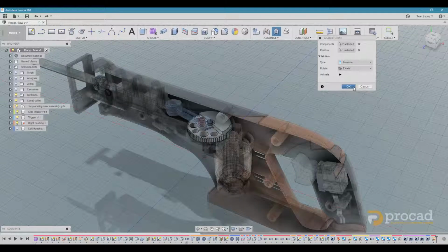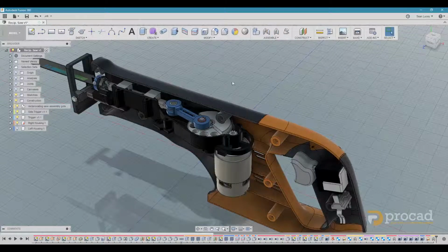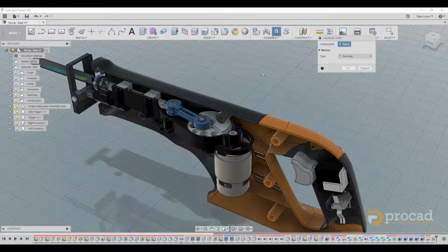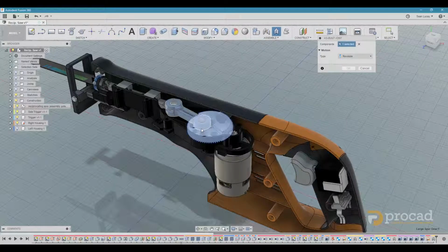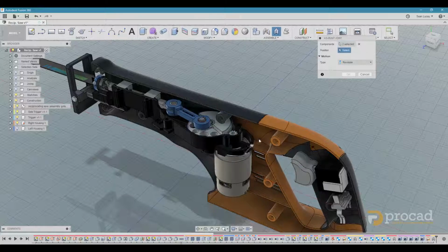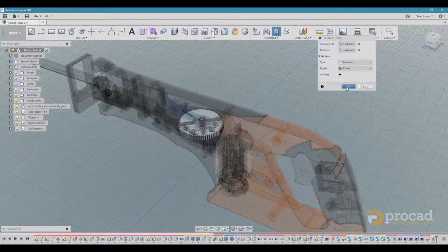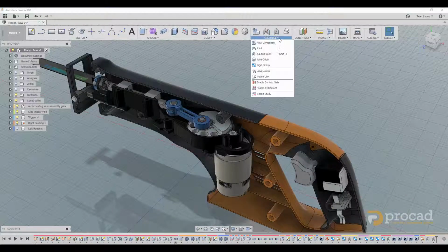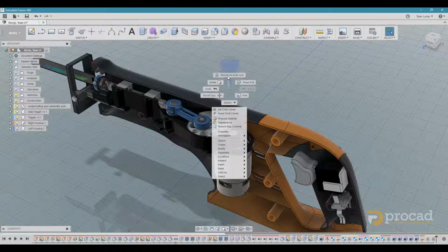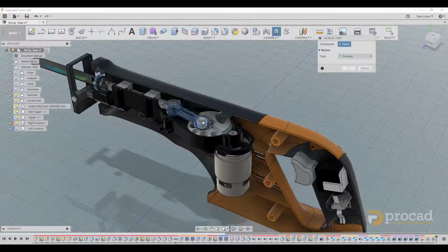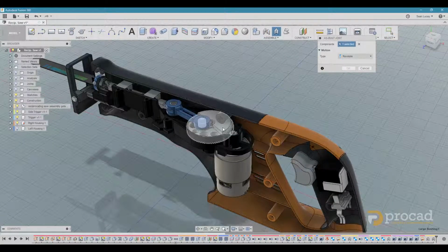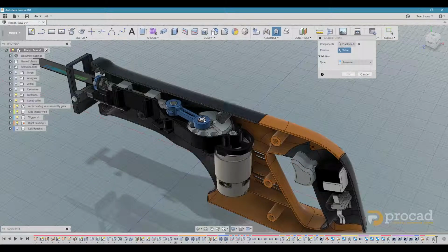As-built joints recognizes how parts move in relation to one another. By selecting this gear and pin, Fusion understands that a revolute joint is needed. Once selected, you will need to reference a plane or point to define the rotational axis. Once a joint is fully defined, Fusion 360 animates the joint to convey to the user the correct motion has been achieved. The movement can be altered by selecting the X, Y, or Z axis.